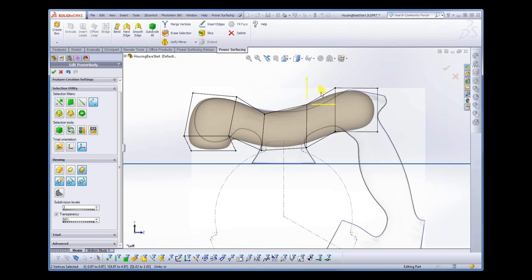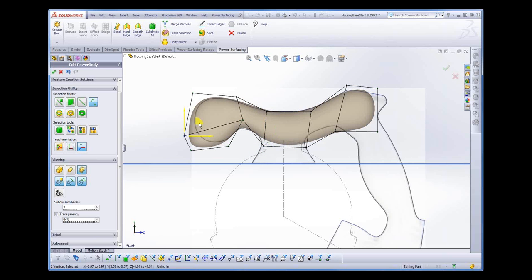So with that showing, now I can start pulling my model into position. And remember, it's very similar to the spline curves. If you move one, the other may move. So you never want to spend too much time at first when you're setting it up. You always go back and refine it after you've got everything closer. And I've kind of found that when you think you need to move something in, you probably want to go to the next one along the line and move it the opposite direction. And it's fairly quick to get a pretty accurate fit on that.